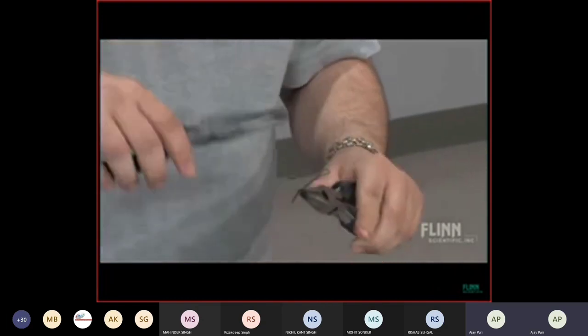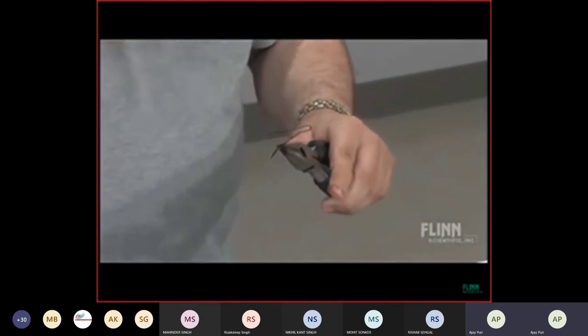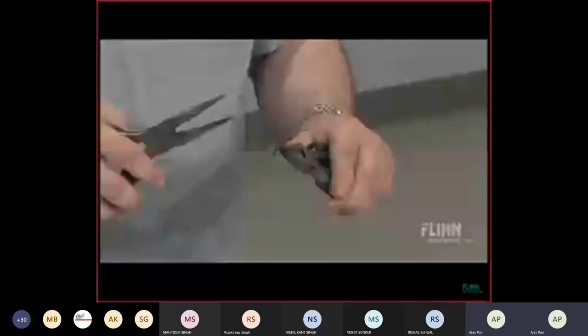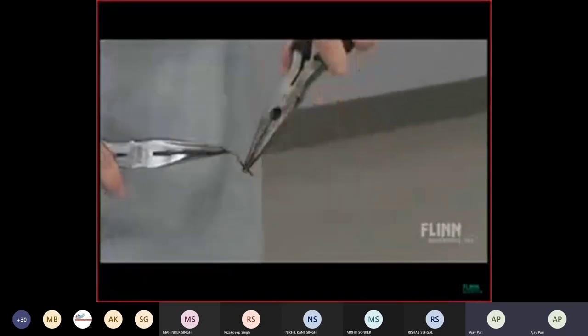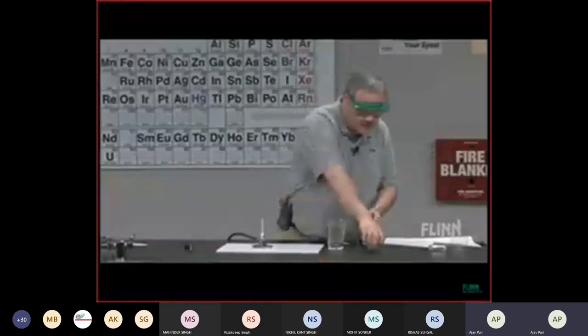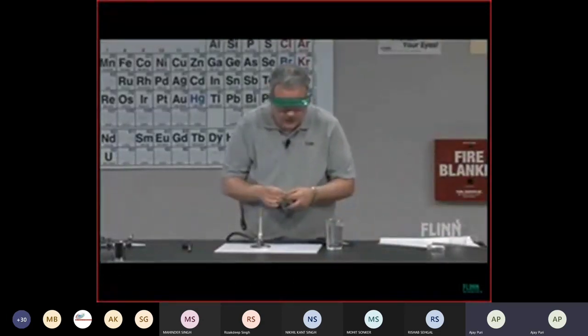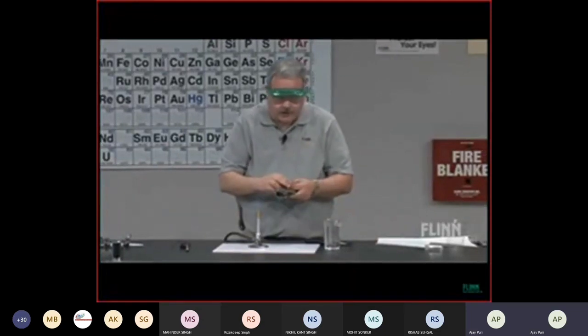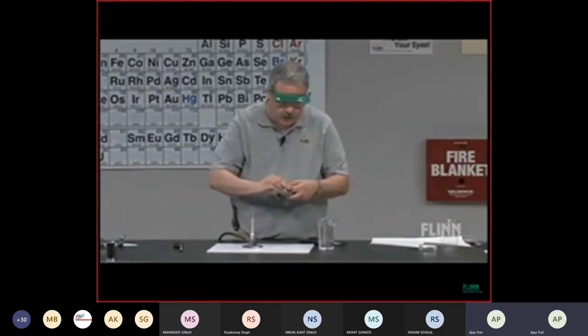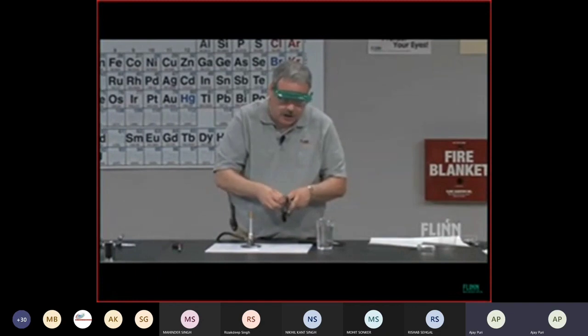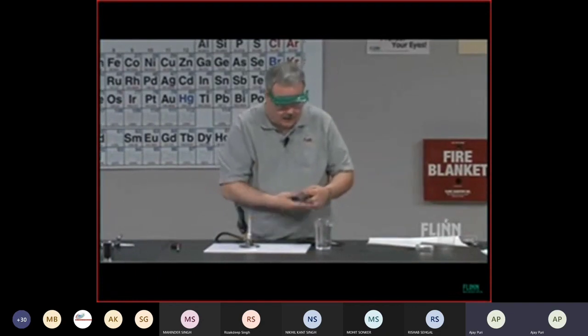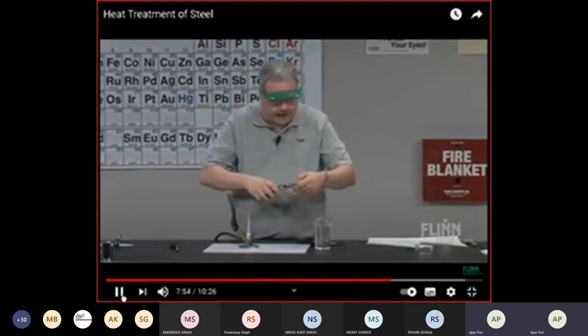Now if I would try to break this right now, it is going to be brittle just like the last one. But what I'm going to do now is I'm going to heat it. Well, guess what? We'll have to do that again. Let me just show you. It is very brittle, and what you want to do is, as you cool it, gently heat it in the flame again and hopefully lose some of that brittleness.